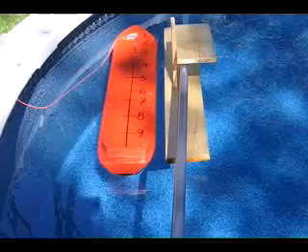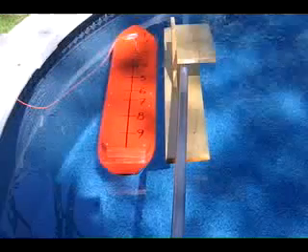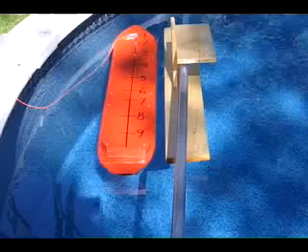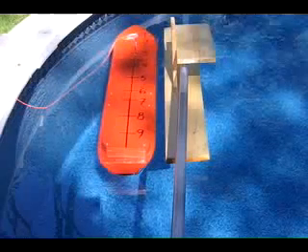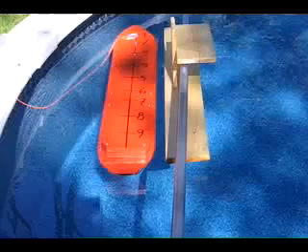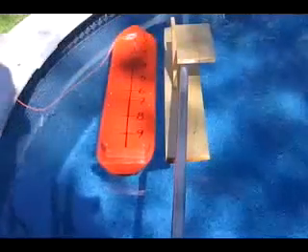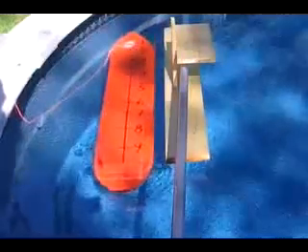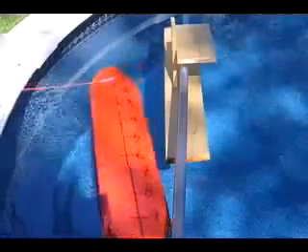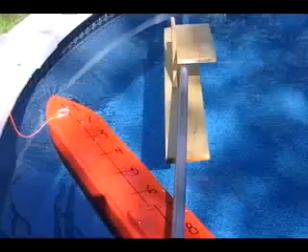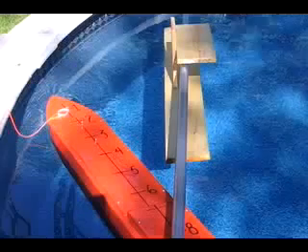In the next situation, the ship is moving astern. Since my homemade model was too basic to be fitted with a bow thruster, I simply use a string to give an efficient side thrust as necessary. The pull is given when a third of the vessel is clear of the dock. So far, so good. The classic pivot point theory does perfectly well.